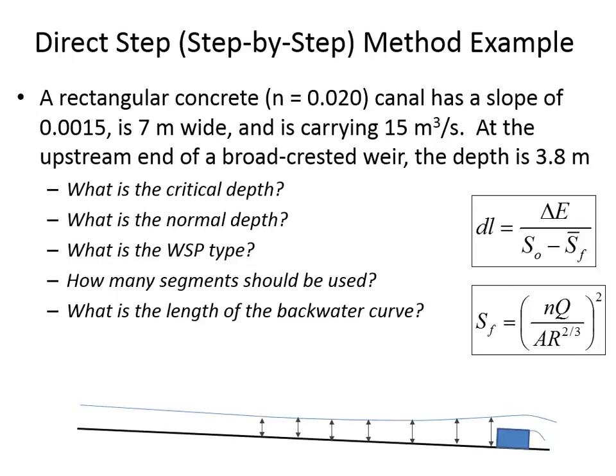But before we do that, we have to get some preliminaries out of the way. We need to calculate the critical depth and the normal depth. And like I've mentioned before, when you're doing non-uniform flow problems, you're always in good shape calculating the critical depth and the normal depth. If you're a deer in the headlights and don't know how to go on the problem, then you'll always be making valuable use of your time by calculating the critical depth and the normal depth.